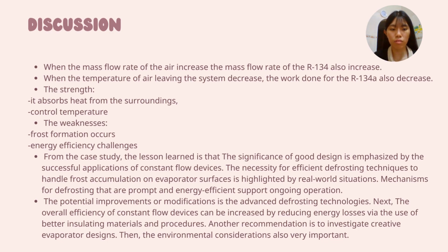When the mass flow rate of the air increases, the mass flow rate of the R134A also increases. The increment is to maintain the efficiency of heat transfer and achieve the steady state conditions. For the second parameter, when the temperature of air leaving the system decreases, the work done for the R134A also decreases. A drop in air temperature may mean that less effort is needed to chill the air.